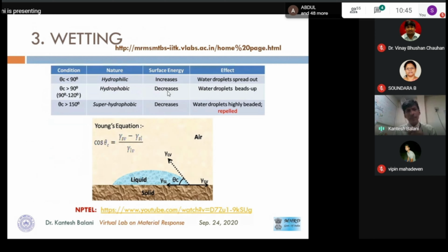Wettability, this is what I just covered. So this talks about hydrophobicity, philicity, and how you can utilize it for even developing, say, windows of a particular building. So how can I make it hydrophobic so water doesn't stick on it and doesn't spoil the visibility through that particular window. So that's where the wetting can be very important. For the offshore structures, it can also provide anti-wetting, and then I can make it an anti-fouling surface as well. Or I can also make the cement not so corrosive to the reinforcing rods, which actually bear the entire load of a building.